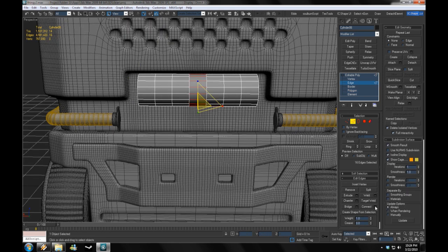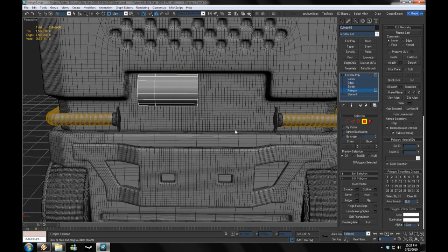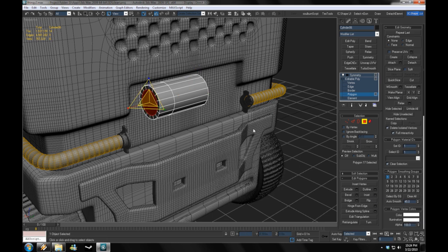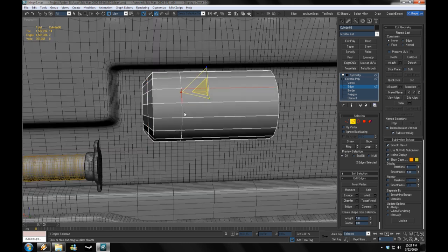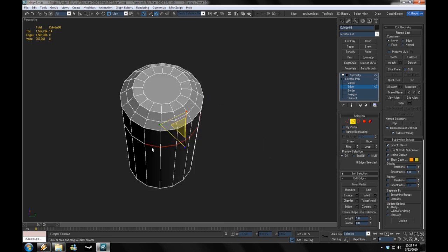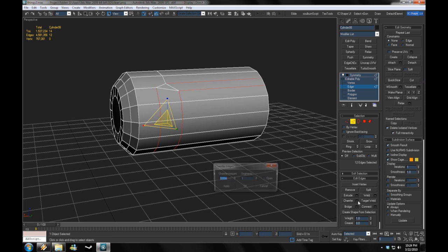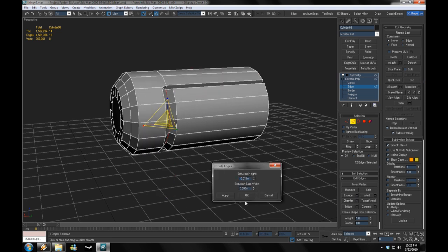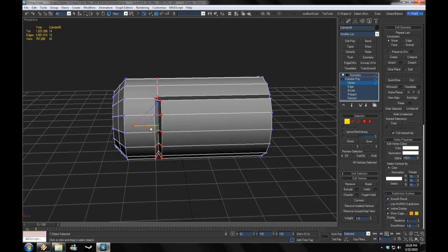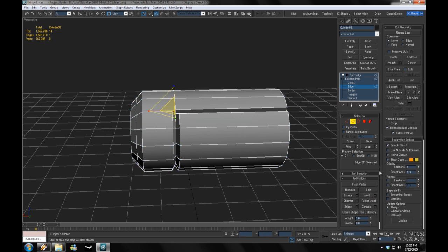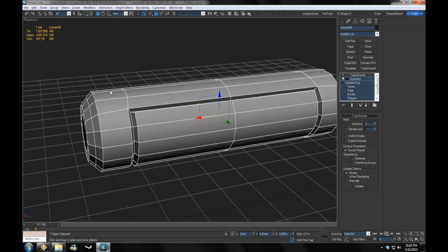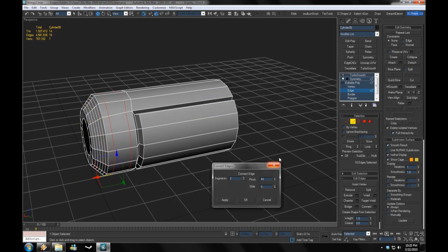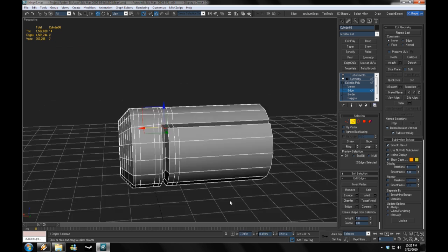So I'm just going to bevel these edges a bit. Just delete extra polygons, use symmetry, and bevel this corner. And add in some more edge loops. And so you can see here I'm selecting some edges which I'm going to use to add sort of this little indent. I always like this shape. I've done this quite a lot on SciFi things, particularly on cylinders. Just defining sort of a panel on round stuff. A hard panel on round things is pretty cool.